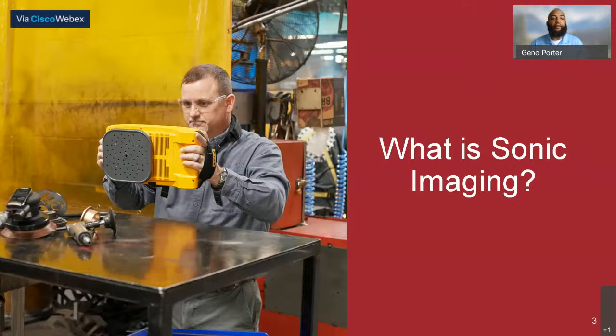In that case, it'll be heat that's hotter than the other devices and hotter than the ambient temperature. If you've worked with one of those before, you can pick up a Fluke ii900 and start measuring air leaks pretty quickly. So the Fluke ii900 is a sonic imager. It is using sound to pick up air leaks or gas leaks or vacuum leaks from a device. So let's step into that.